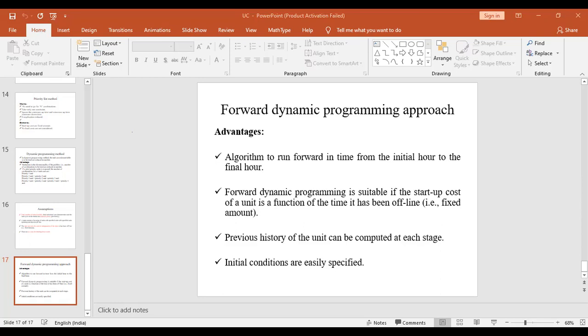Coming to constraints, there are two sets of constraints. One is the equality constraints, and the second is the inequality constraints. In the equality constraints, we concentrate on the basic load flow equations, which can be stated as the real power generation equation and the reactive power generation equation. The inequality constraints are a set of generator constraints, voltage constraints, transformer tap constraints, transmission line constraints, and network security constraints.